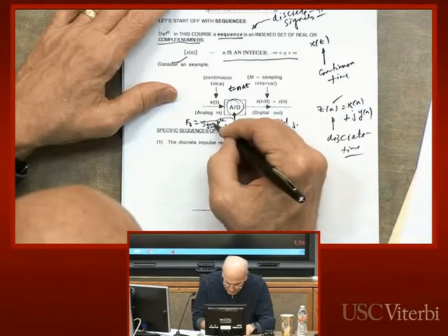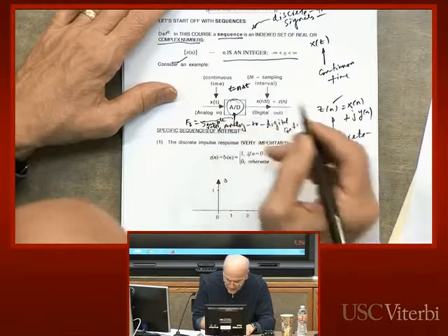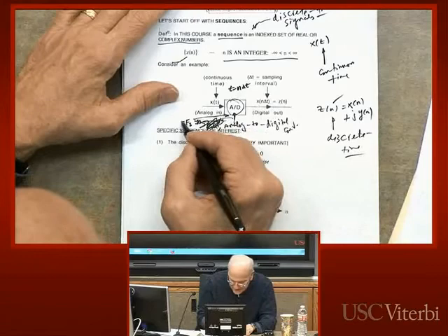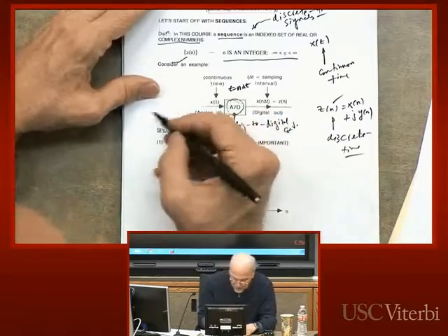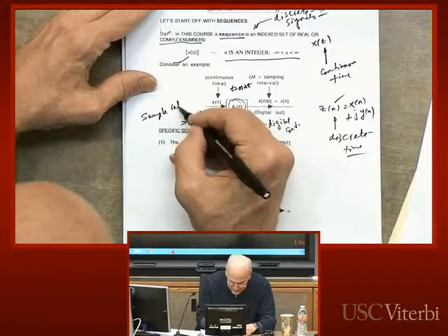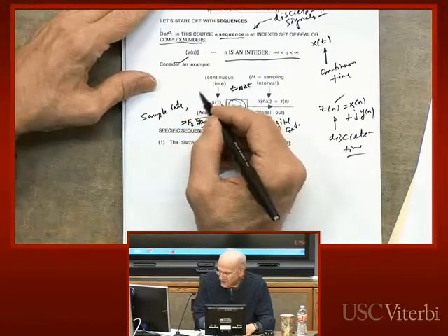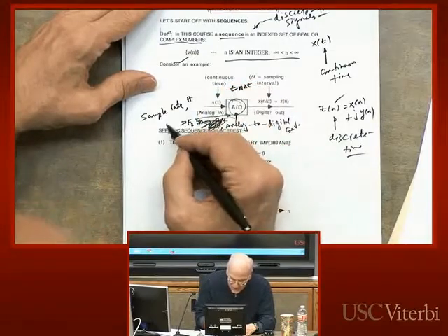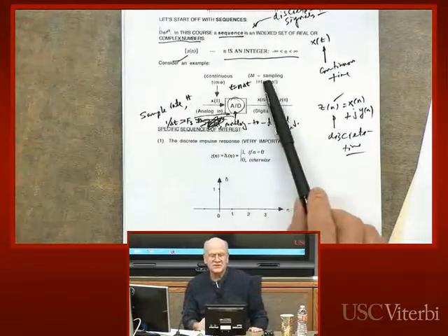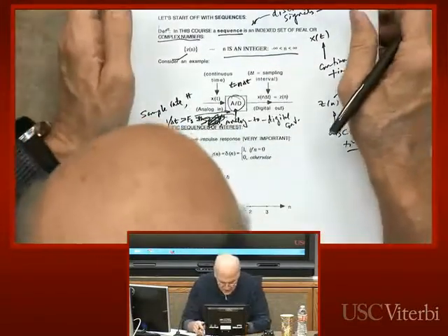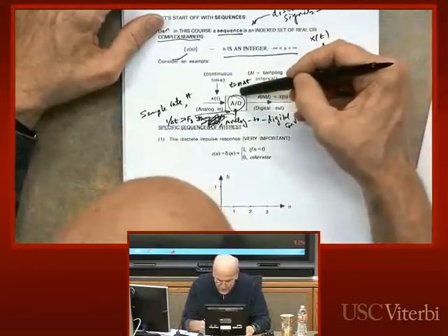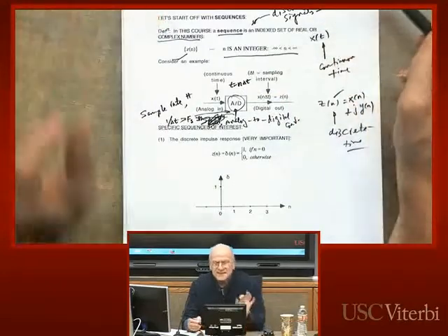Here, let me say this. F sub s is called the sample frequency or sample rate, and that's in units of hertz. And by the way, this is also equal to 1 over delta t. So if Fs is in units of hertz, delta t is in units of time, seconds. So wherever I wrote it, t equals n delta t. Delta t is the sampling interval.